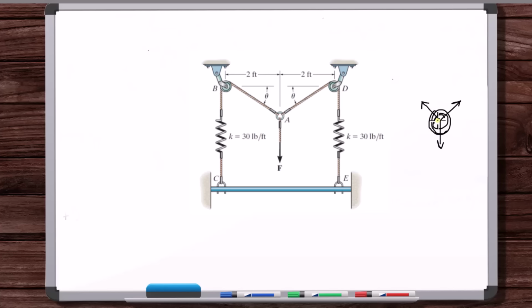So yes, the ring itself is a rigid body, but the idea of a rigid body is that when you go from zero load to any load within the working range of the system, it holds. You could apply a huge load to steel and it'll twist, but that's outside what the system is doing. But here, if we released the load, the forces would go.